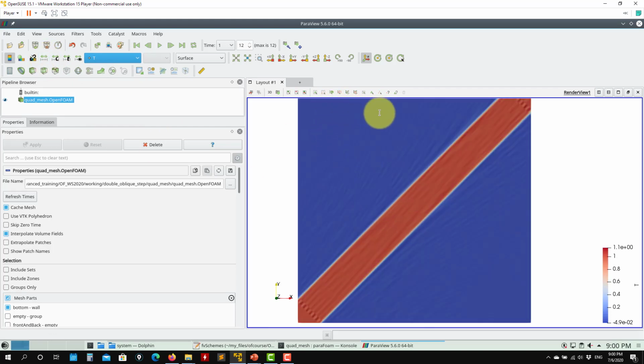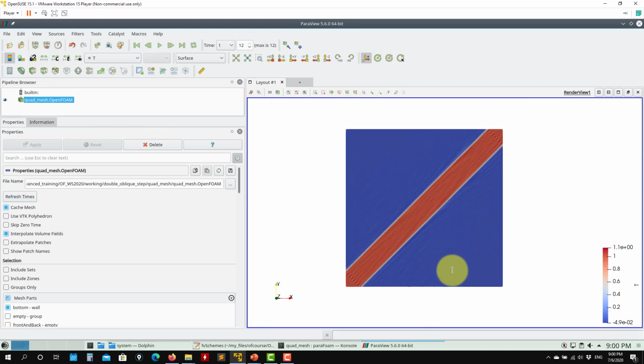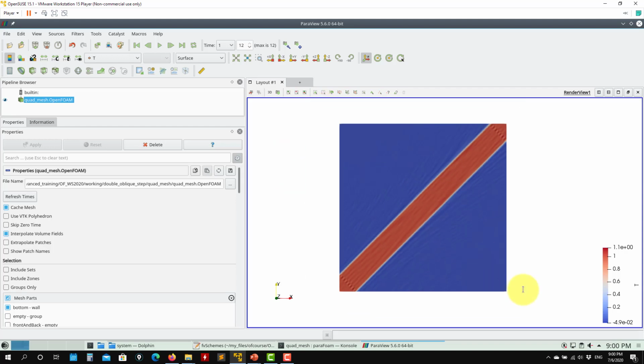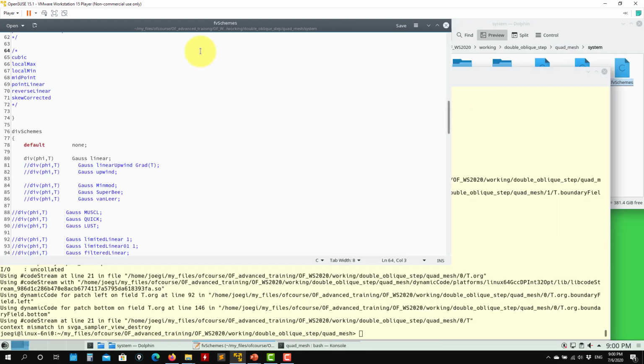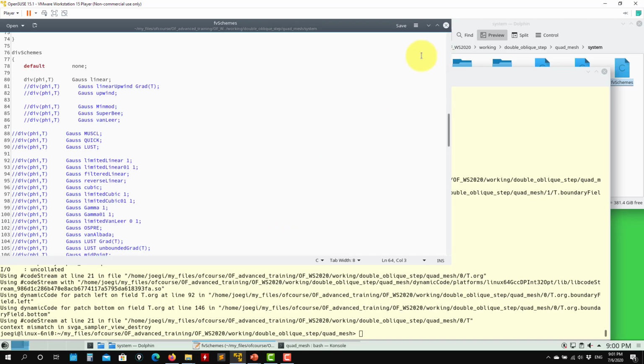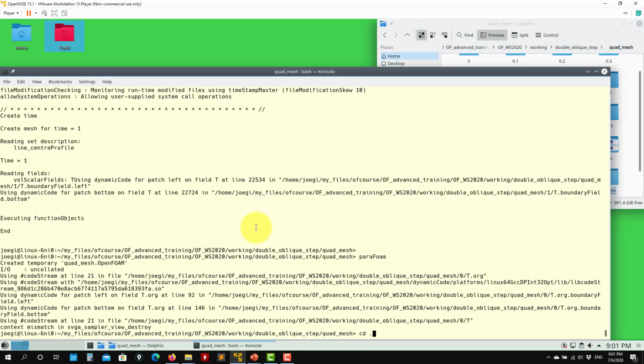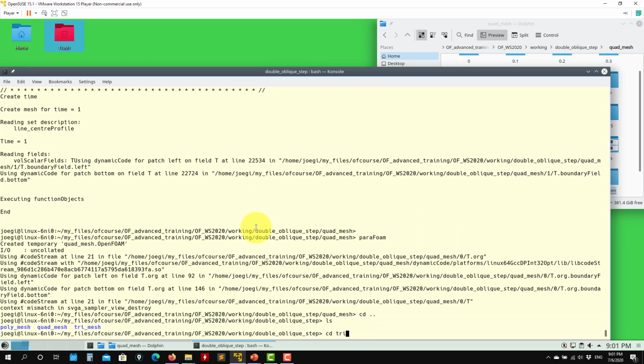Okay, see that everything, even here where you have 0, is being propagated and it has an influence far where you shouldn't have anything. So those are the problems of the oscillations. And it will be the same effect when you see some unboundedness. When you visualize somewhere, you will see very large values or some wave propagating in your domain. Okay, so we worked it out with this perfect mesh. Nothing to do there, but let's move now to a triangular mesh.